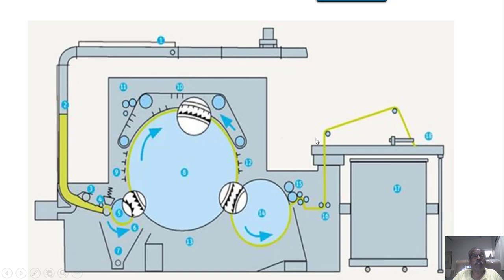Now the same is depicted here, the various parts involved while this is done. On modern carding, you see here the spring loaded feed system, the feed plate, the assisting plate. Then you have a sensor here, transducers are used here so that the regular flow of material will take place, and that sensed material which is now being regulated will be taken to the taker-in zone here.